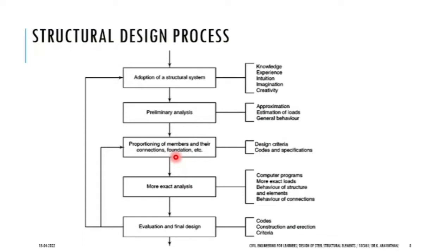You can do it through a certain process. You take out the water when you construct the outer wall. For the whole foundation pit, if you are constructing the outer wall, the water will not come inside and you can drain all the water that is there, on all 4 sides and the bottom. Everything you have to seal with water-proofing or concrete, then you can build the structure.